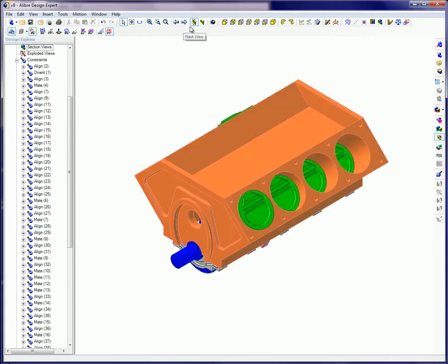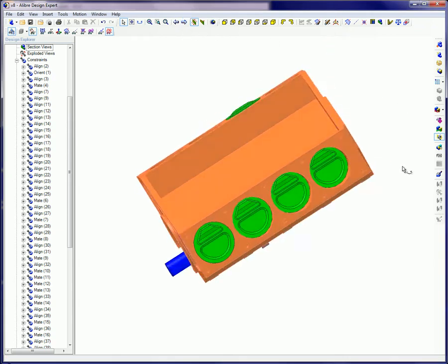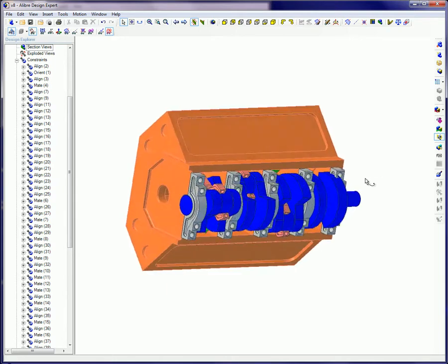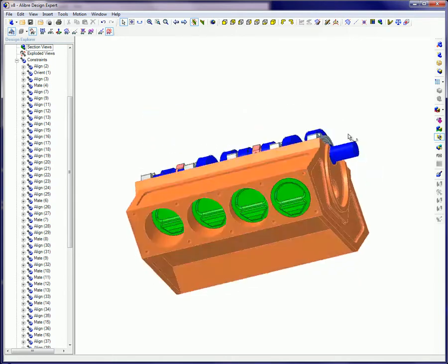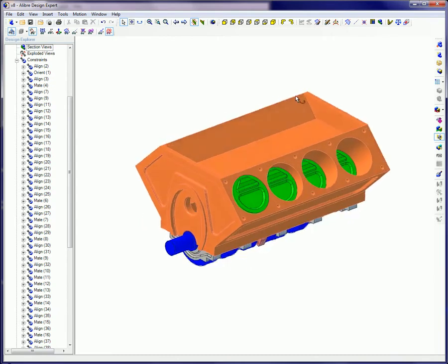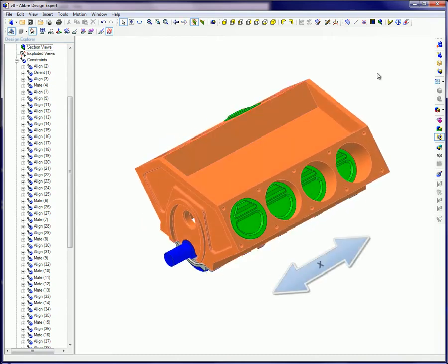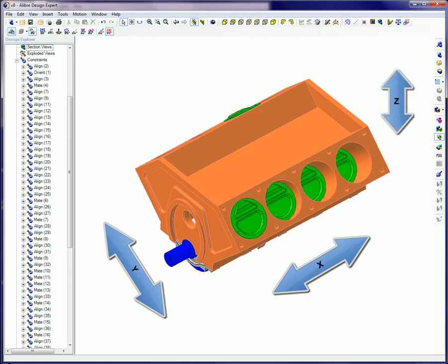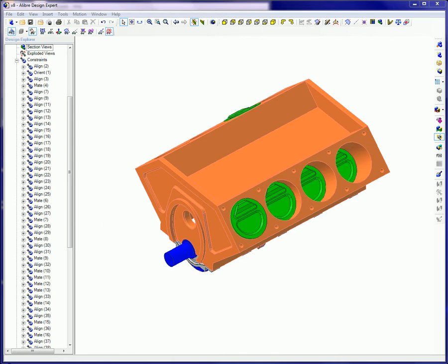The alignment assembly constraints define a relationship between two selected items. Constraining parts in an assembly also limits or disables the freedom of movement within an assembly. Typically, three constraints are needed to fully define and constrain a part, but in many cases, parts need to be less than fully constrained, so the part is free to move along a particular axis.